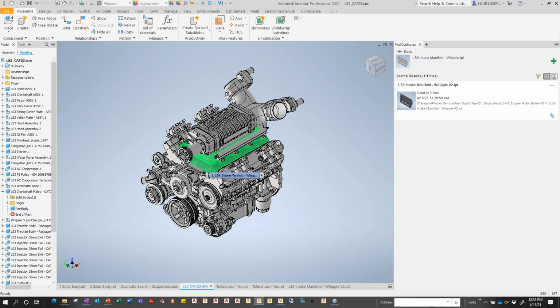So when you're replacing parts, as you do with Inventor today, replacing a part is not a new feature. Replacing a part using the duplicate search, though, adds more power to that feature. We want to confirm our constraints, that everything has successfully resolved itself. So that is the duplicate search feature working, how to configure it, how to configure from the Vault, how to create reports and understand the information that we're looking at, and how to work inside of Inventor.